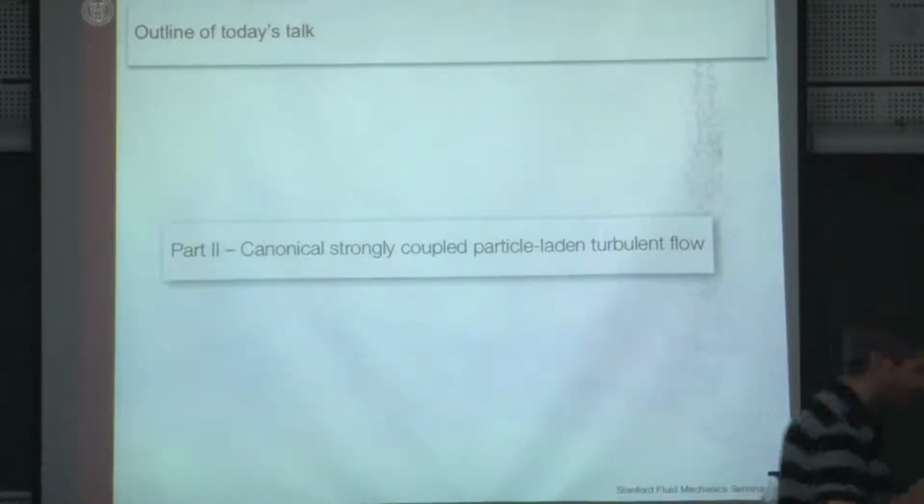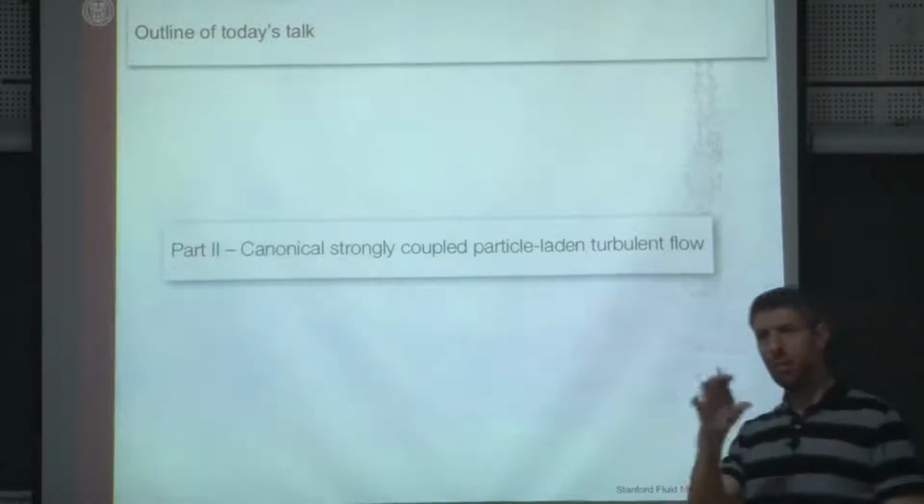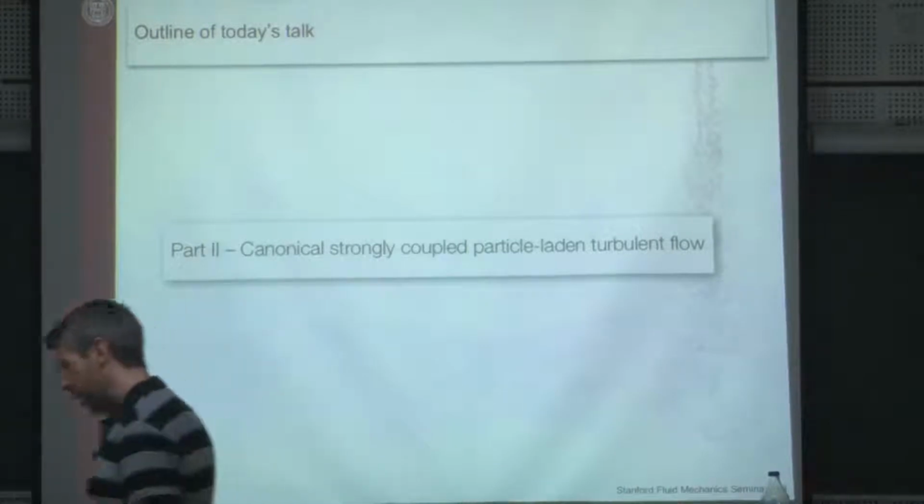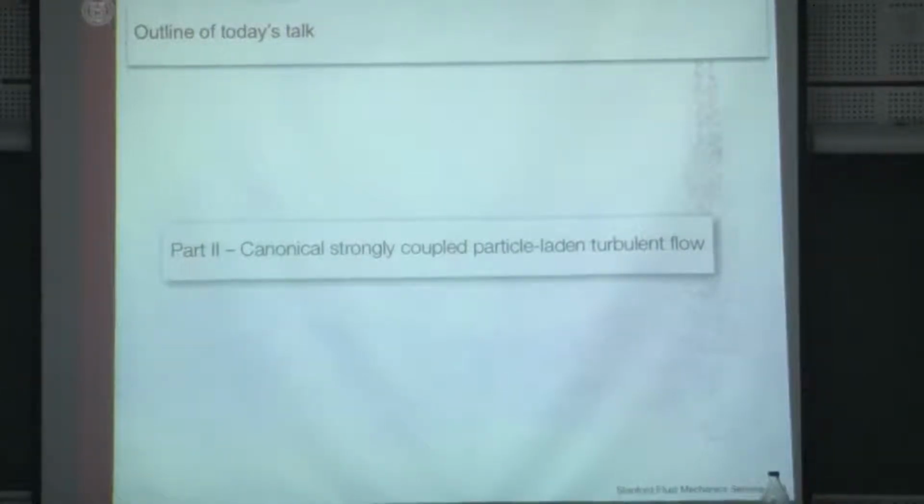There's more, we can talk some more if you want. People have started doing very detailed simulations, typically in Couette flows, in simple Couette cells, looking at whether we enhance or eliminate turbulence, typically looking at neutrally buoyant particles, to simplify the story a bit, fairly large particles, full particle resolved DNS, okay? And they've started putting together regime maps for that as well.